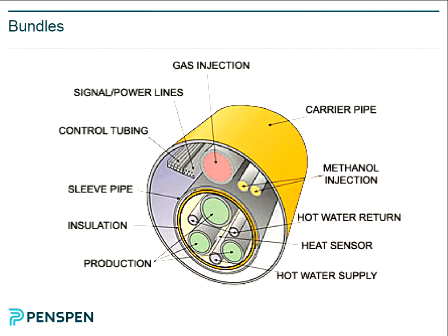Okay, so with inert seawater. Is it possible to run a pig inside the production pipe? Yes. As far as the pipeline is concerned, it doesn't even know it's inside a bundle. It's connected with conventional spools. So from the inside point of view, the pipe is like any other pipe, basically. Absolutely no problems running the pig. You can't obviously run a pig in the annulus, but that's full of inert water.